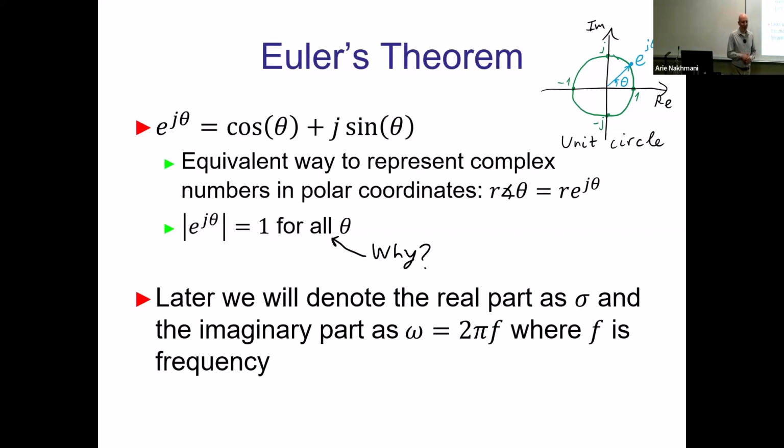Just to remind you what we learned previous time. We talked about LTI systems, linear time invariant systems. We showed one particular approach to characterize this type of systems using delta response or impulse response. Using impulse response, you can practically draw any signal with multiple deltas in series, and then based on linearity and time invariance, you essentially can compute the output of the system using convolution integral, or convolution sum if it is a discrete system.